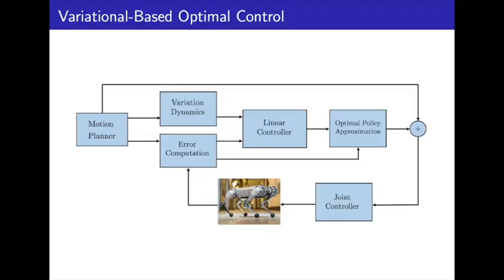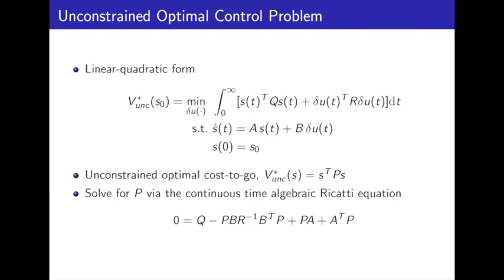The two primary components of the proposed control framework are, first, a linear controller that solves an unconstrained optimal control problem, and second, a quadratic program that uses the output of the linear controller to approximate the optimal input-constrained solution. The controller, referred to hereafter as the VBL-QP controller, employs a control strategy aimed at minimizing the cost to go of the system, according to the following cost function.